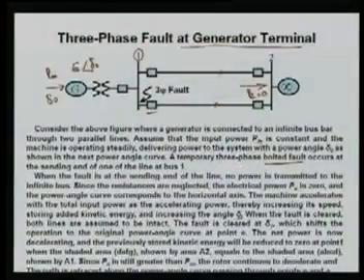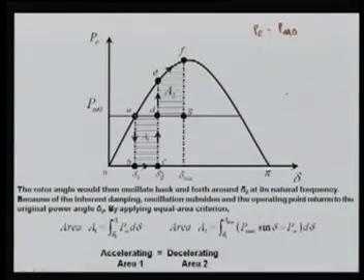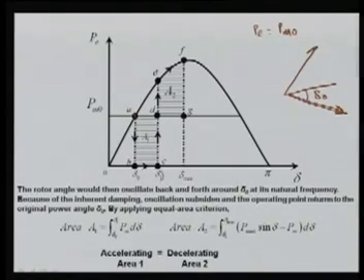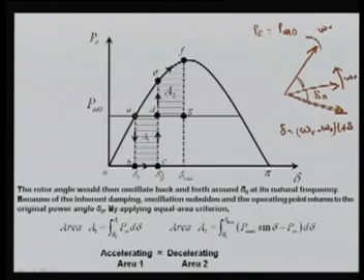The delta is an angle. Let's suppose this is your reference angle, any arbitrary reference angle. Here this is your delta naught, and your machine here has two rotating fluxes; this is your synchronously rotating one, and this is the actual rotor speed omega r, this is omega naught. So this difference, that angle, means your delta is omega r minus omega naught, times t, plus delta naught.